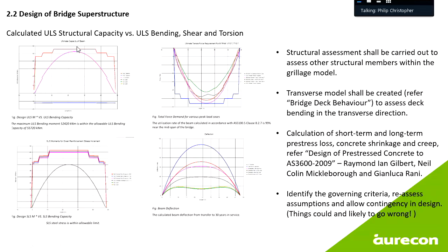As you can see, there is the bending capacity, the shear, and the torsion and moment combined effect. I've listed the clause in the AS5100, so you can see the formulas and do a bit of number crunching. Once you get familiar with the process, you will be able to calculate from one end of the beam to the other, which means that you don't have to throw all the reinforcement and strand along the full length of your beam. You will be actually trying to reduce some quantity for your client as you go. So this is where the truncation point happens. You have a splice and you have a reduced size of the reinforcement.